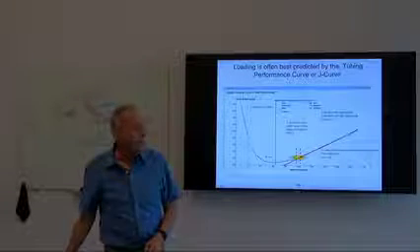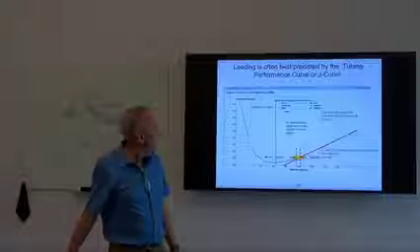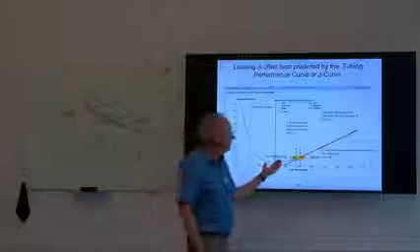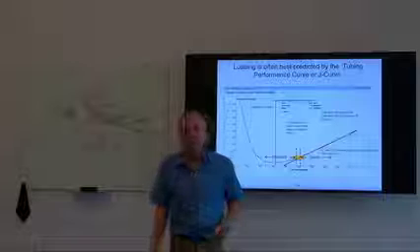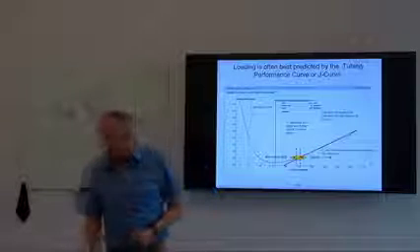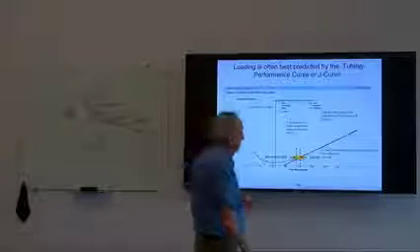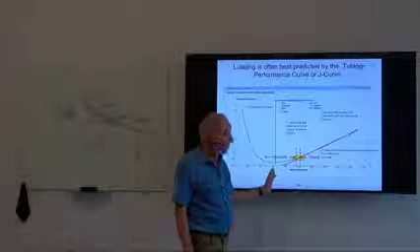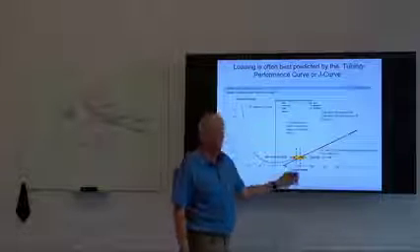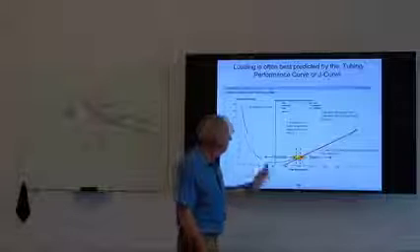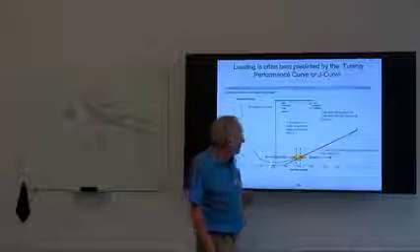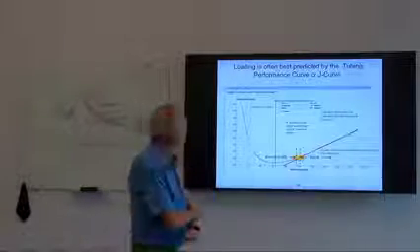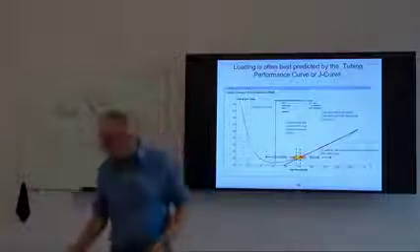And so we look at this area instead and say, aha, we have a different range where we have a transition from unstable to stable flow conditions. This represents a very different gas rate than if we simply looked at the minimum. In this particular case, it's around 1 million cubic feet per day versus about 650,000 cubic feet per day as predicted by the minimum point on the curve.